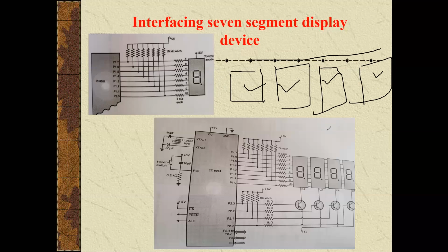All the ports of the 8051 will be used. In this case, no other device can be interfaced to the 8051 microcontroller. So all 4 7-segment displays are interconnected with each other and connected to the 8051 microcontroller. Hence, we multiplex the 7-segment displays. To control them, we utilize one characteristic of the human eye, called persistence of vision.